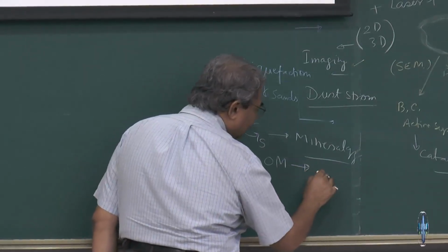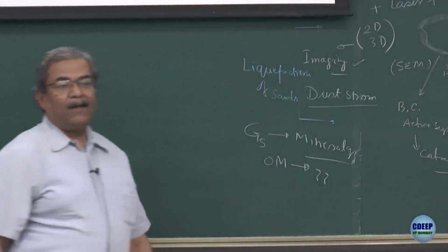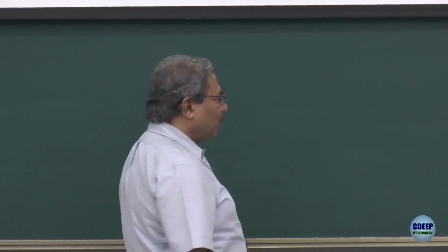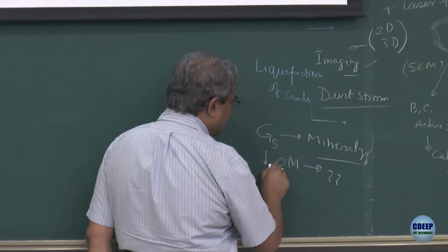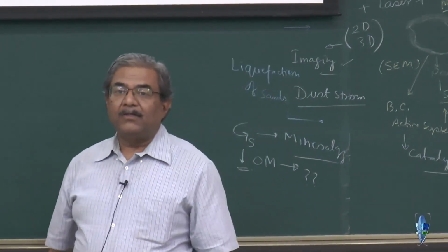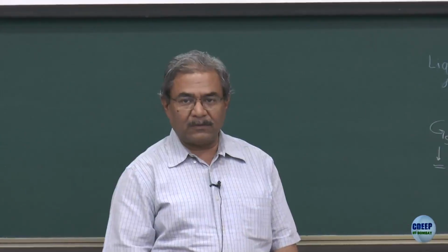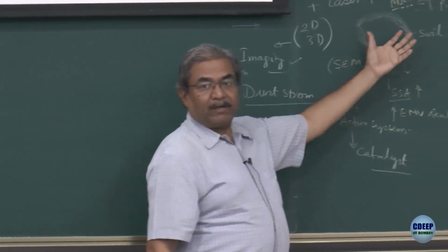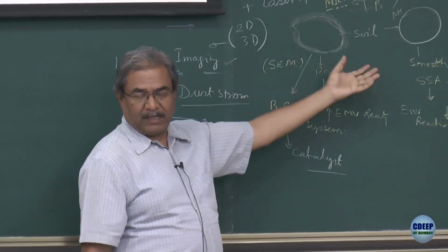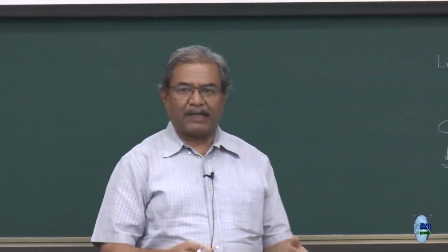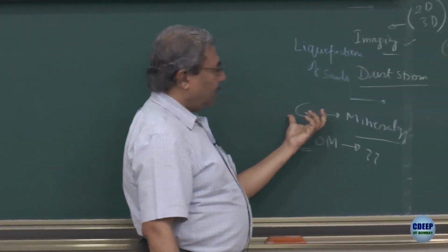Okay? So, what does this organic matter do? Organic matter is lighter material, mostly cellulose. What is it going to do? It is going to drop the value of Gs tremendously. So, the system is going to become very light. So, a question which concrete technologists would ask you is, out of the waste material which you have given them, whether it can be utilized for some purpose in concrete or not. So, one of the indications would be Gs.